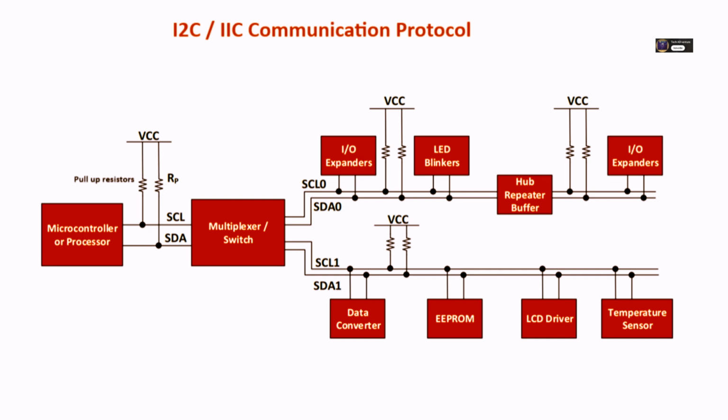If the pull-up is too strong, the device might struggle to pull the voltage all the way down to a valid 0 level. This can cause unreliable communication where zeros aren't read correctly, or in extreme cases, could even potentially stress or damage the output drivers on the chips if they're constantly fighting a strong pull-up. On a scope, you might see the low level not quite reaching ground.